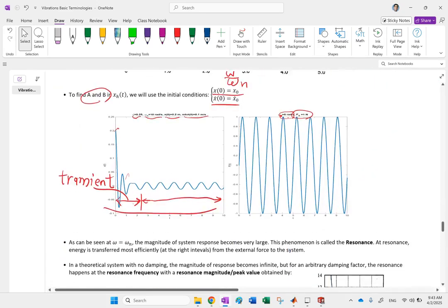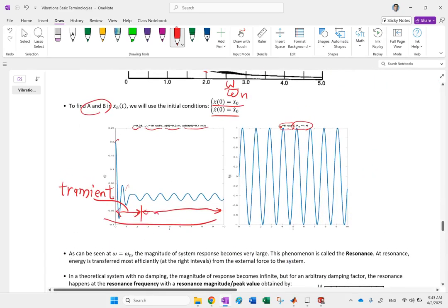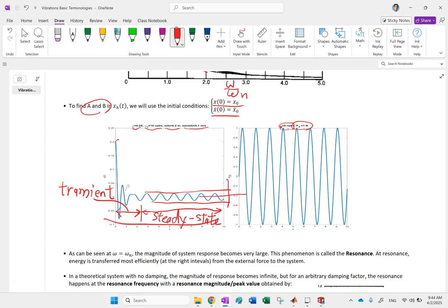So that is what you can see after some time. This portion is called the steady state response. This is the response that, regardless of how much time gets bigger and bigger, will not change. Here you have a fixed magnitude x and a fixed phi. So half of this amplitude, from here to here, that is your x. And then there is, of course, a phase shift between this signal and this signal, that is phi. Okay, and that is a function of all of these parameters.